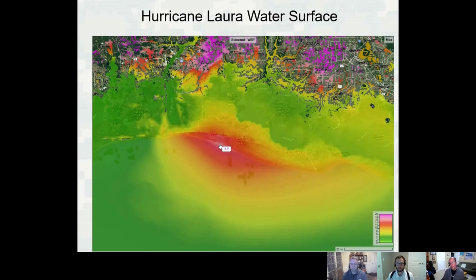Obviously, the Weather Service is outputting both historical winds, which is what this was from, and they also do wind forecasting. So if you're in the middle of an event, you're going to get wind forecasts from people like the Weather Service, or some of these atmospheric models might be predicting what's going to happen over time from an atmospheric standpoint. So you might just take the wind field computed from an atmospheric model would be another approach. Yep. But as far as historic data, you want observed winds. Most likely in our country, in the U.S., you're going to get that from the National Weather Service.